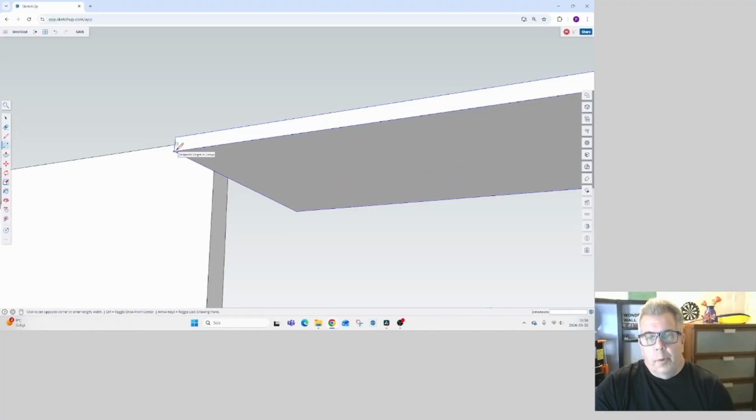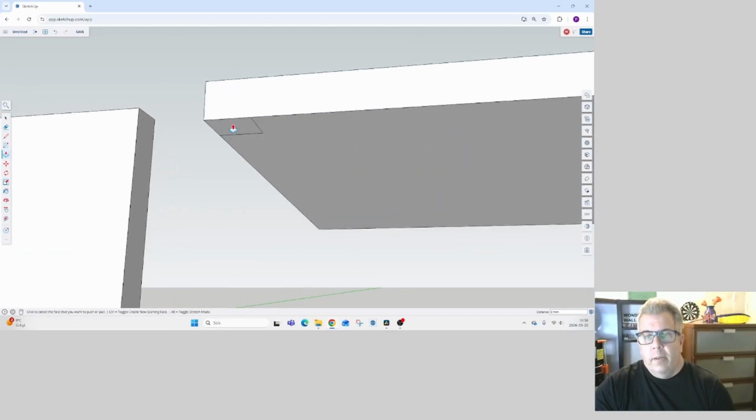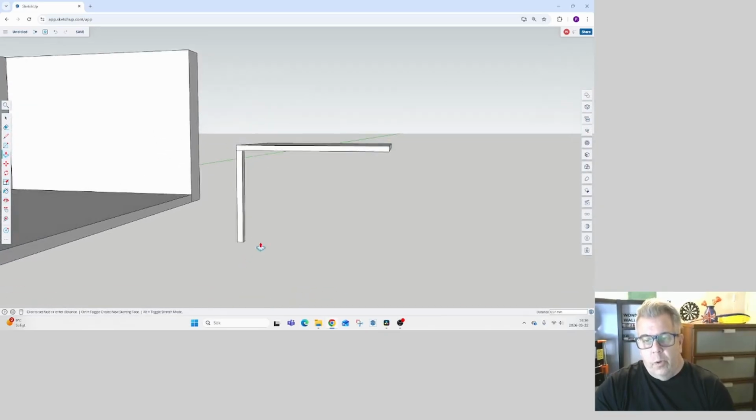A rectangle: my first point is the corner point, and then just click out the rectangle somewhere, and then the dimensions. I'm going to make it 40 millimeters by 40 millimeters. Enter. Like so. And to give the legs a thickness, it's going to be push-pull. Click on the surface and zoom in a little bit. Click on the surface, and you see I can move it down. And if I don't know where to end here, I can just use the finished floor as a guide. As soon as I hold it here on the edge in group, that's where I want my table leg to be.